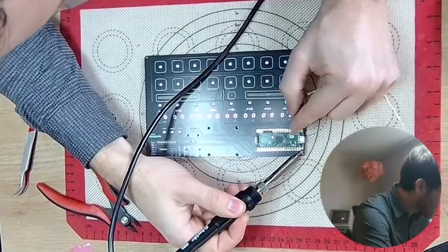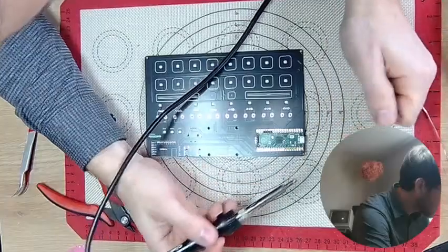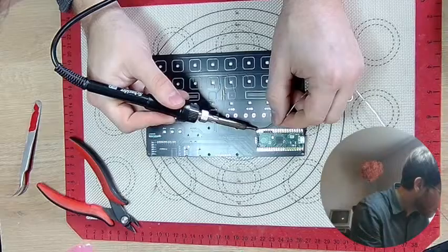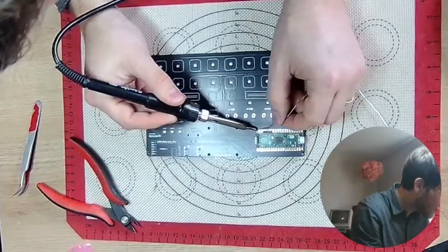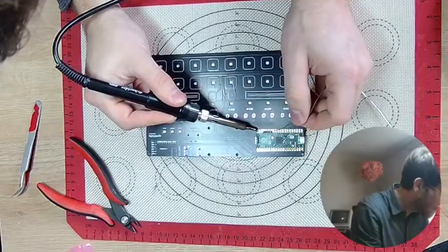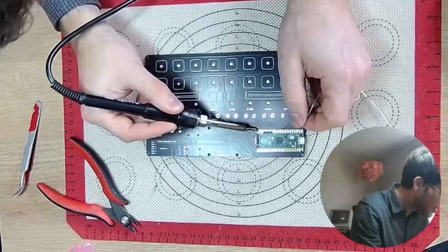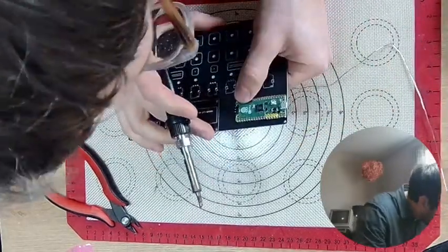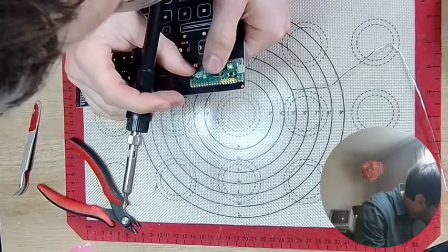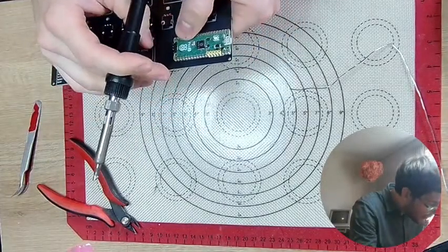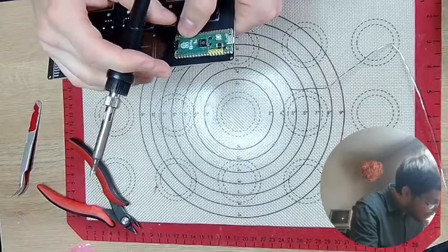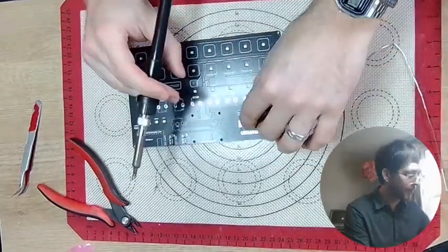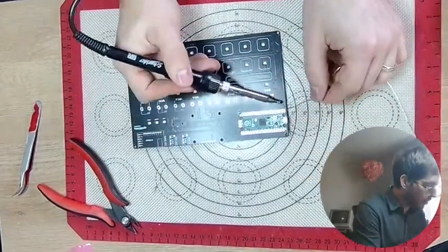Now, you don't want to put too much solder if you don't have to, right? So I've tacked the corners, well, one corner. Oh my God, can I tack the other one? Come on. Sorry, iron's just probably getting hot. Okay, and then let's check. How does this look? I'm seeing the holes are lining up. Yeah, good enough for me. So once you get those, you can basically take these little pin headers out and then get to work.